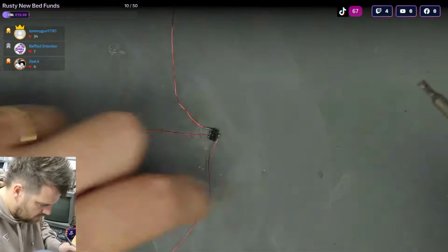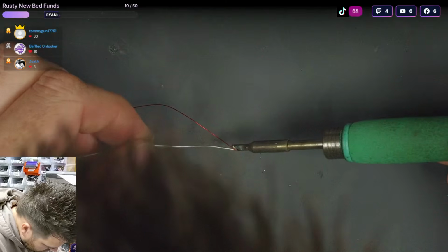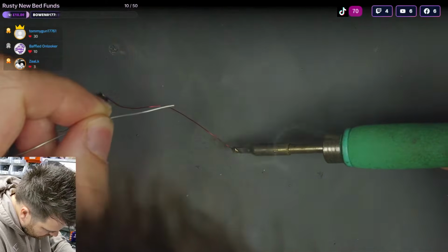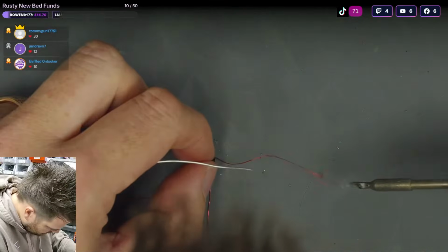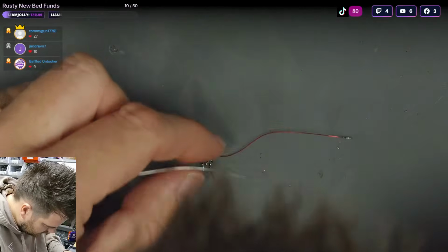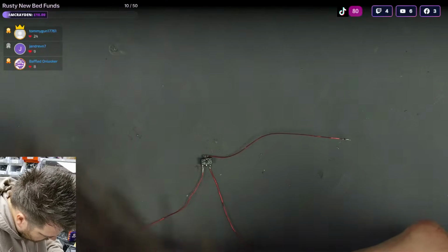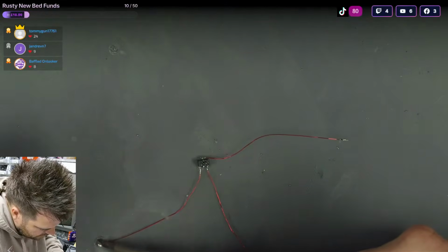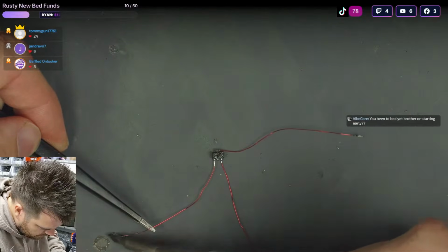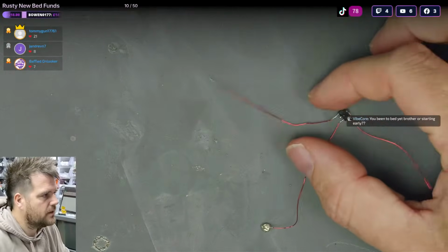Right, and then when we strip these ends, I will fold them over and make a bit of a ball so that we can actually grab onto them with the component tester, or just try and get extra solder to stick to the pins is the goal. But I'll normally make a little loop in the wire and then fill it with solder to make like a little tab. That's how you make these thin wires thicker. So we've got this thin wire.